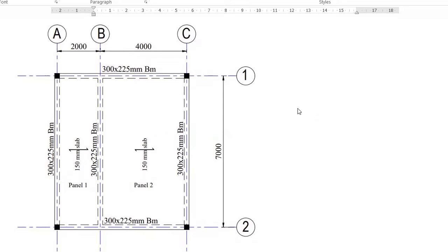Now, I spoke of the fact that your beam can constitute a point load on another beam last time. I never knew that I had one in my material. So if you check beam B, I believe everyone can see the beam on grid line B. This is what I mean. This beam you see my cursor on, right? That beam has no column support.